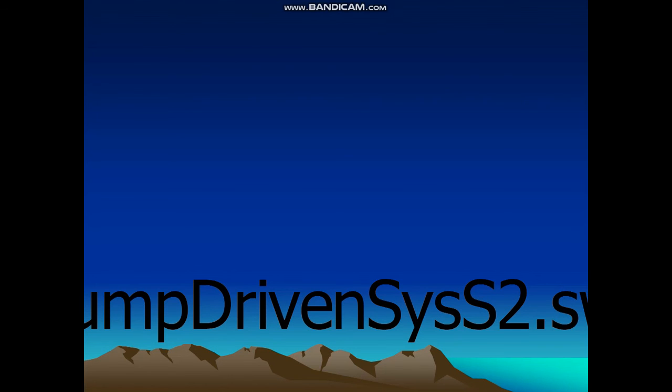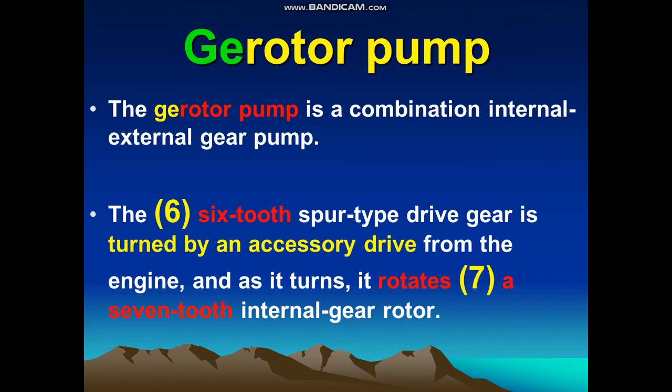Gear rotor pump. The gear rotor pump is a combination internal external gear pump. The 6-tooth spur type drive gear is turned by an accessory drive from the engine, and as it turns it rotates a 7-tooth internal gear rotor, and this is the gear rotor.